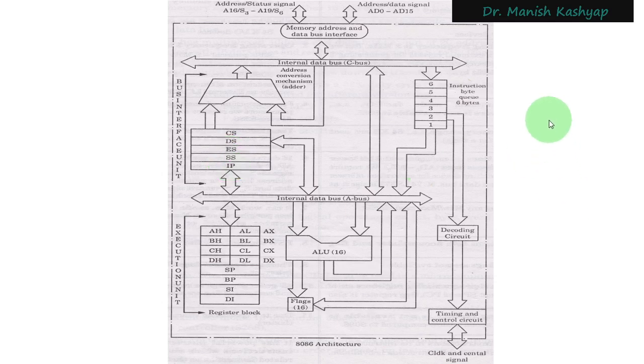So in the externally interfaced memory, there are these four different sections, and their addresses are kept in the code segment, data segment, extra segment, and stack segment registers. The names are similar. These are the pointer registers that you have got here. These will be pointing to the necessary locations in the external memory.